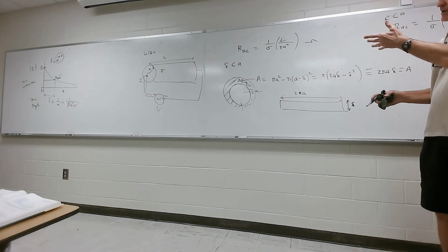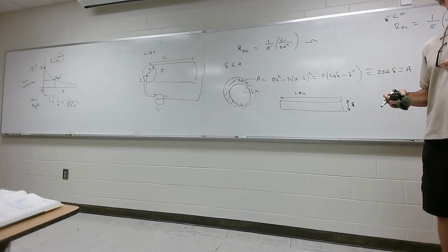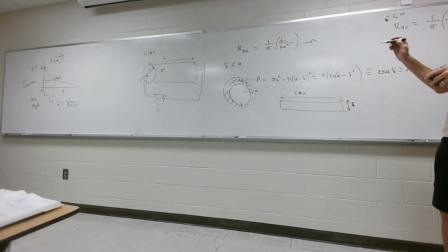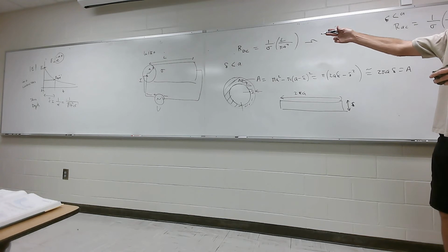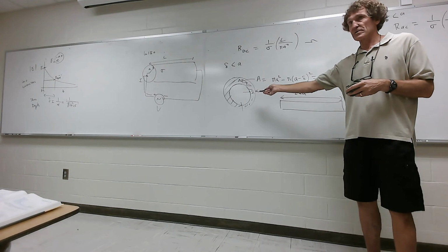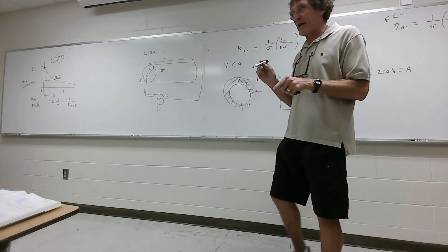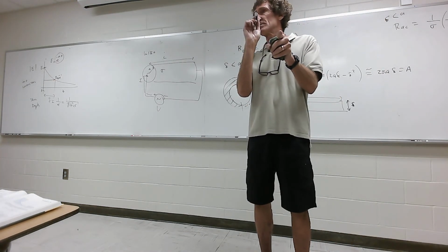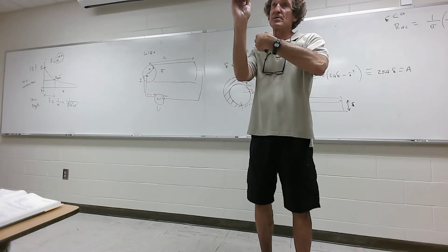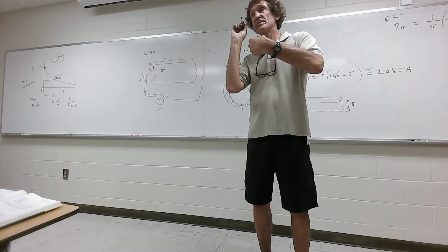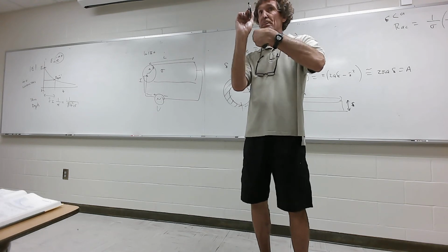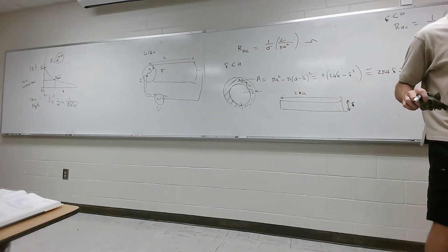So, I'll give you some problems where you calculate the resistance for different types of geometries, but fundamentally, the only thing you're doing is seeing, first of all, if the skin depth is important. In other words, if it's small compared to the radius, and if it is, then you have to find the reduced area the current's flowing through. And remember, anytime you have wire that is driving a signal differentially, like a standard communication channel, you have current going this way and returning in the opposite direction at the same time, so you have to get the resistance of the top and add it to the resistance of the bottom per meter. Y'all follow me on that, class? Okay, just remember that.